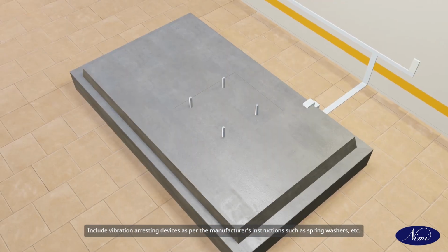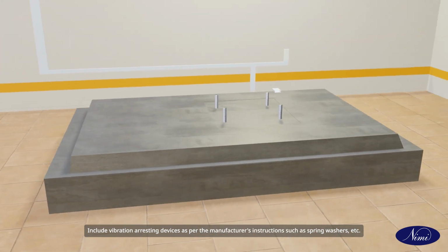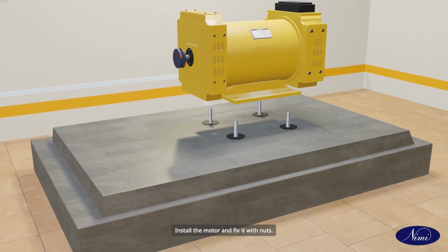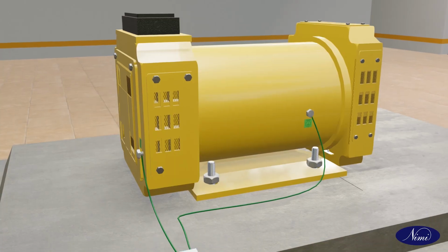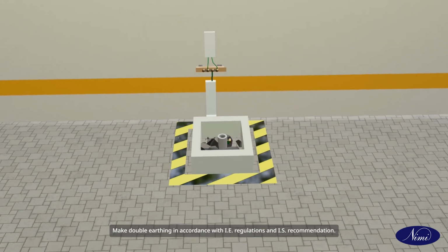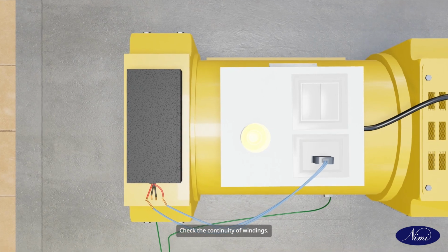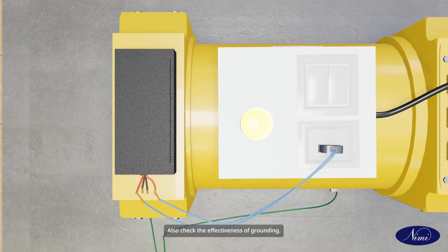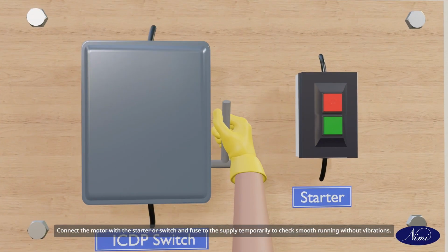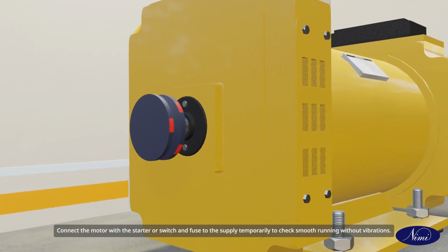Include vibration arresting devices as per the manufacturer's instructions, such as spring washers, etc. Install the motor and fix it with nuts. Make double earthing in accordance with IE regulations and IS recommendation. Check the continuity of windings. Also check the effectiveness of grounding. Connect the motor with the starter or switch and fuse to the supply temporarily to check smooth running without vibrations.